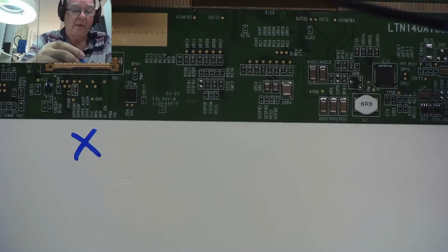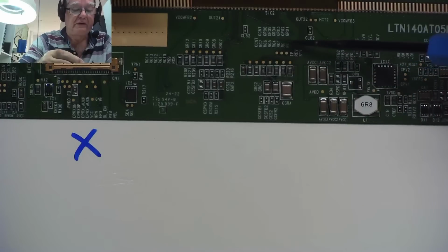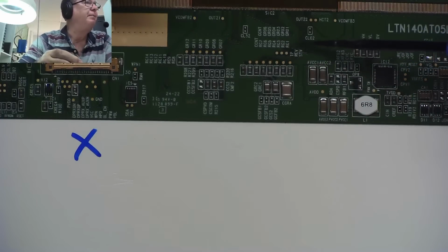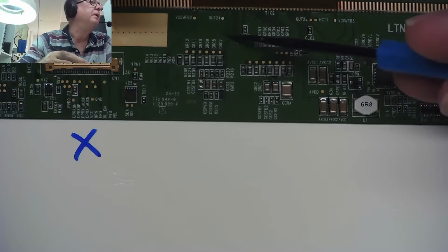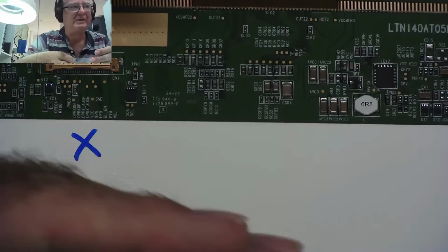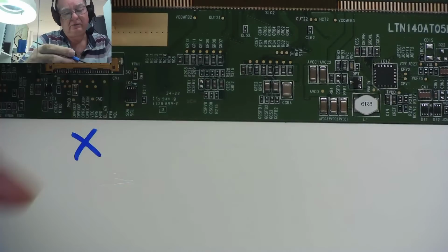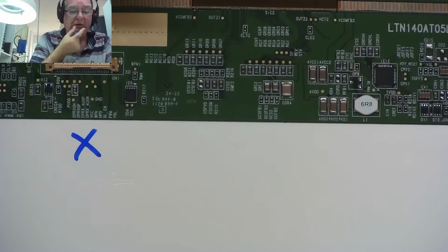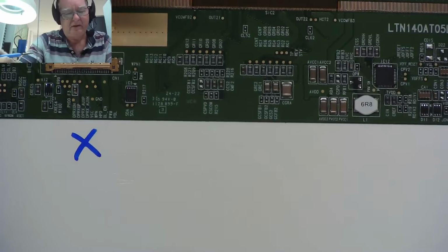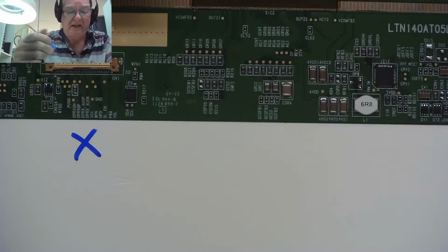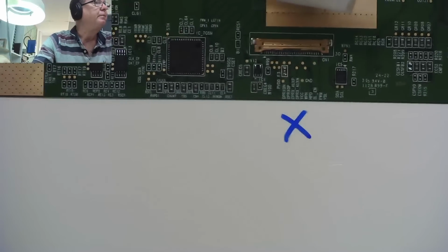In fact, I'll make a note of all these resistors because they're numbered. And I reckon if I put the voltage against each pin in the same order of the numbers here, like GR01, GR02 and so on and up, what we'll get is an absolute ascending list from the lowest to the highest, or highest to lowest, on those voltages, and that'll tell us the gamma chip's okay. But also, to be honest, the voltage on both screens are the same, and the gamma's working because you get the picture. So I honestly think that's working. I could make that list just out of interest, but it would just be for interest.